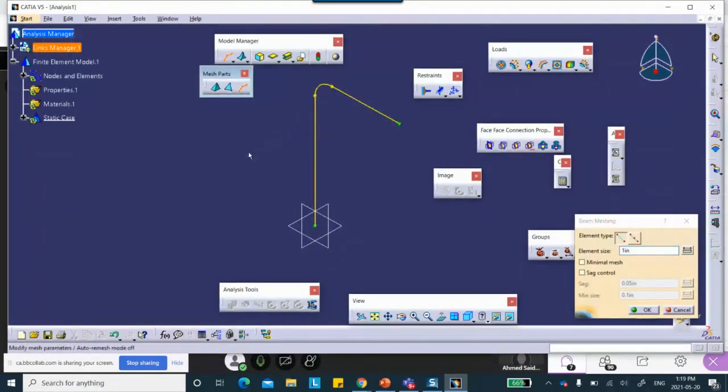You select it, it turns yellow, and what this element size is, remember, you break it up into little one-dimensional elements. So that's the size. If you say 1, it means that one of these elements is going to be 1, 1, 1, 1, etc. Now, if this radius is 1, this is going to be a terrible element here, because this whole radius was 1. So I'll change it to 0.5. At least I track some of the curviness here. Okay. Let me make it 0.3.